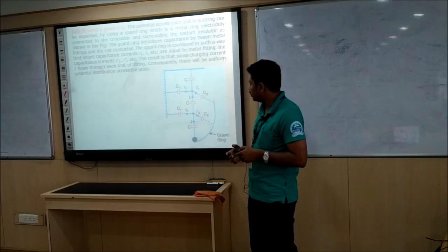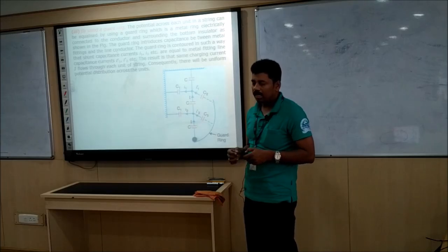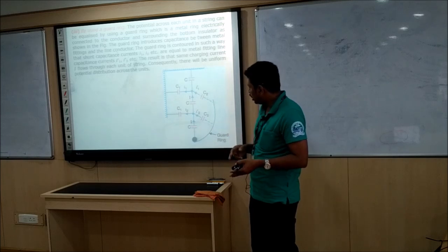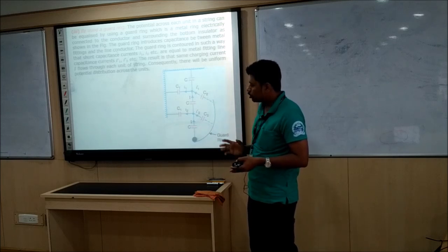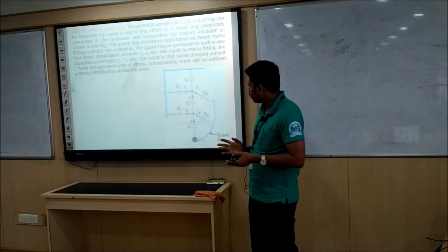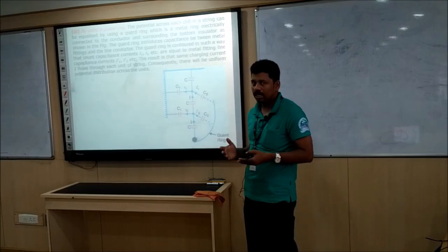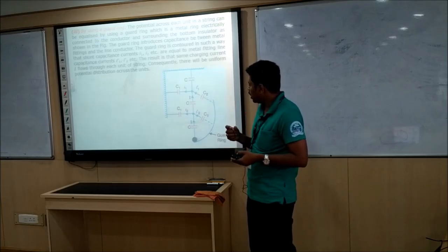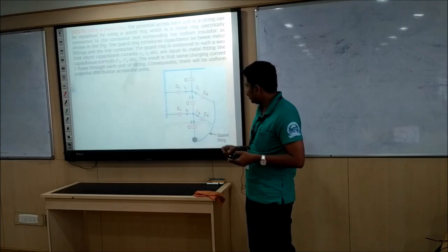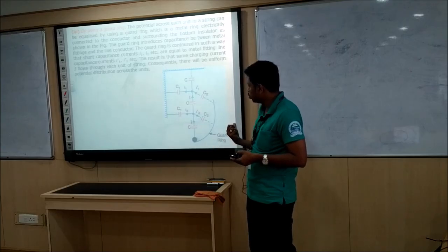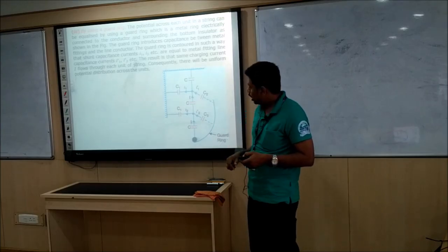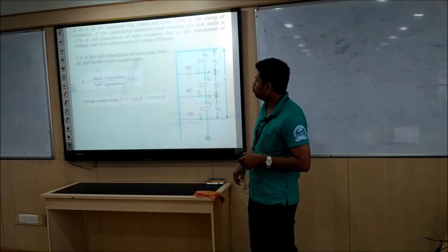Guard ring is a ring, which is nothing but a conductor connected at one end to the conductor and at the other end to the atmosphere. This will form another capacitance, so that if both the shunt capacitances match, the effects of C1 and C3, and C1 and C2, are cancelled, and the uniformity of the supports will be there. Otherwise, I can say that C1 is cancelling C3, and the effect of C1 is cancelling C2, so that only self capacitance is there in the system, and that way the voltage distribution is uniform.